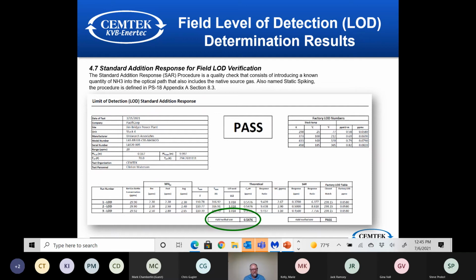So we've had multiple customers report that they have far better control of their process now with ammonia injection on their emissions, because when they get a slip number, they absolutely believe it. On coal-fired units, they tell us that the moisture reading that we get is very accurate. And when they see that moisture number going up, it means one of two things. Your optics are dirty, or you have a tube leak in your boiler.